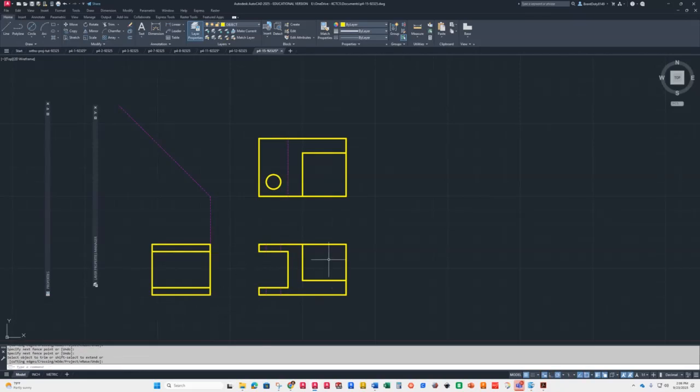All right, now we got to figure out where this angled line is, right? Well, I'm going to go ahead and change back to hidden because I need to draw hidden. And I'm going to draw a line over to here because that's where it would be. And then I need to project this one over and down to right there. And then I can just connect back over to here. All right, so there's that. Okay, the last thing I think I need to do, besides my center marks, is to draw my lines from here over, down.